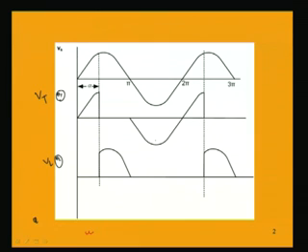input voltage, and it will be continuing till after this point again alpha angle is exceeded, because alpha is the delay angle. So, after this point again it will have to wait for alpha, and till then the input voltage will be equal to the voltage across the thyristor.